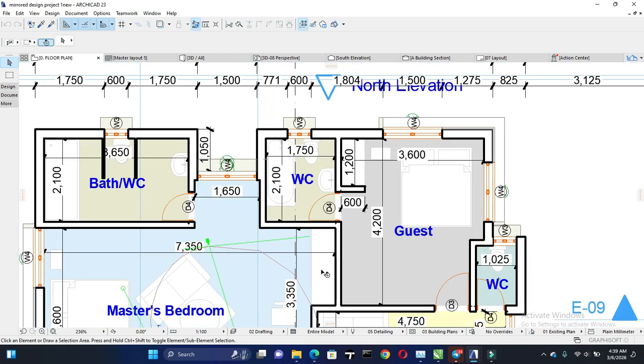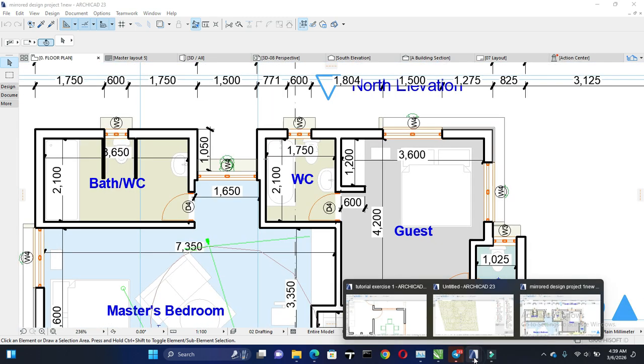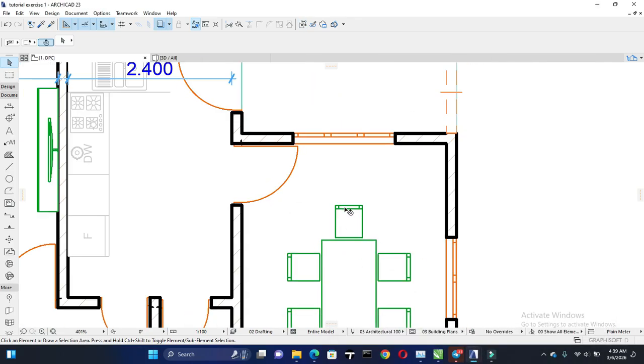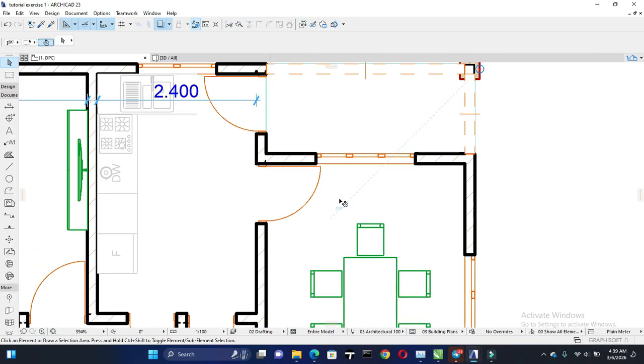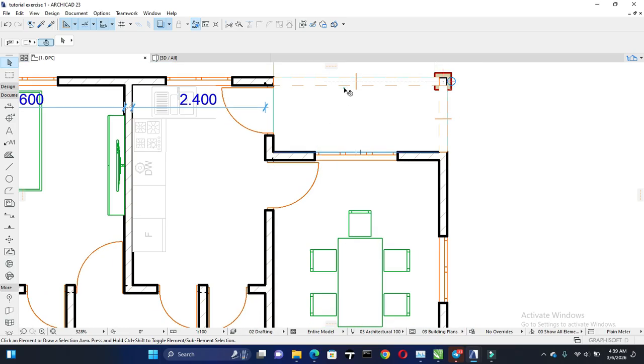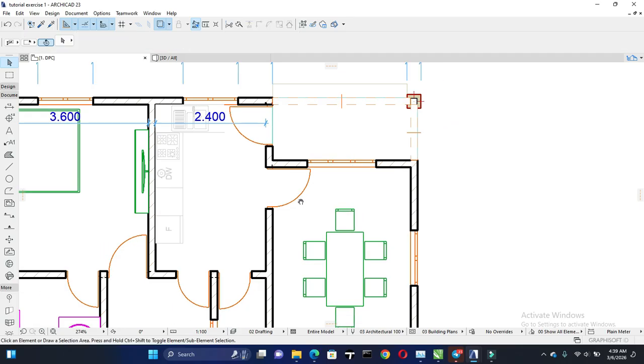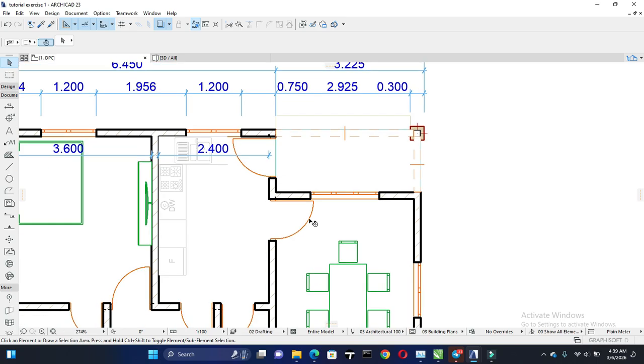So that's the same thing for changing the line weight, the line color, the line type, and all. You just have to know the line you are working on. And how do you know the line you are working on? You select the components that you want to change the line for.